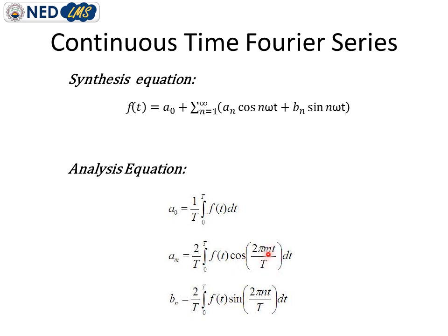So it is m times f, which means a particular frequency or an integer multiple of that frequency. If you want to determine whether that component is present in your complicated waveform or not, you can determine it with the help of this equation, which is An equal to 2 over T integral f(t) cos(2 pi m t over T) dt. Similarly, you can find out the component Bn and its strength with the expression written last.